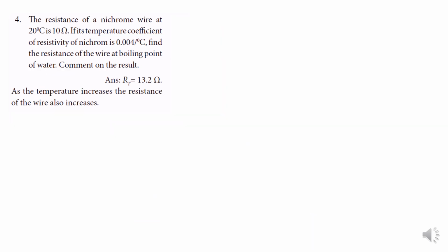So question number 4. The resistance of a nichrome wire at 20 degrees Celsius is 10 ohm. If its temperature coefficient of resistivity is 0.004 per degree Celsius, find the resistance of the wire at boiling point of water. Comment on the result.